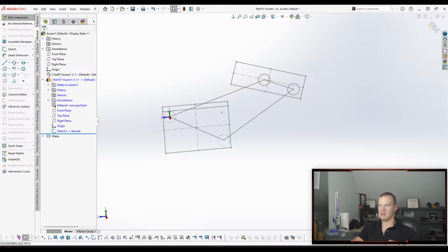To me, inserting just the sketches seems more stable, I guess. I don't know. I have wanted to do a comparison on some project where I take the same project and model it using skeleton sketch and master model, and see which one's faster and more robust.